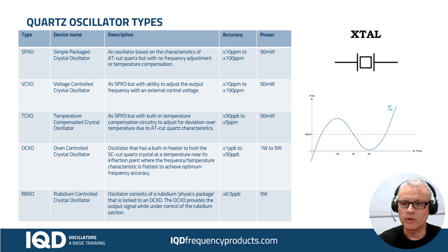And what we're going to do is cut through a lump of quartz crystal rock, and we're going to cut at an angle of 35 degrees 15 minutes. That angle corresponds to what we call an AT cut, and the curve down at the bottom there shows the temperature behavior of an AT cut crystal. What you see is it's rotationally symmetrical about 25 degrees with a rollover point at -20 and +60 degrees. And so that's what it is. That's how the product behaves over temperature.